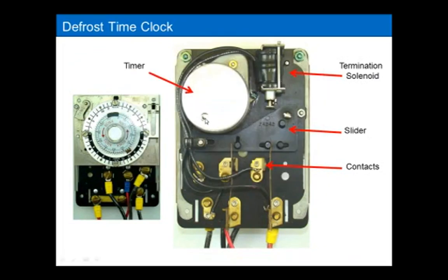If you were to flip this over and then safely energize that timer, and be careful when I say safely, these are all live hot terminals here. So if you were to somehow safely, and I'm going to make sure I say safely again, safely get to the point where you can turn this time clock on while it's flipped over, you'll see the time clock spinning in here. And it's a nice way of identifying that that time clock is working.